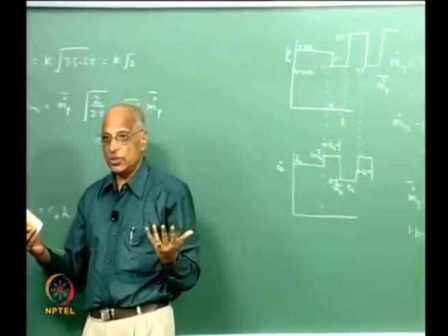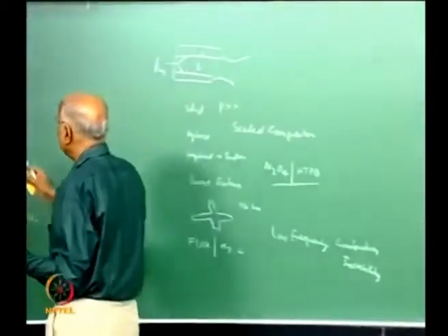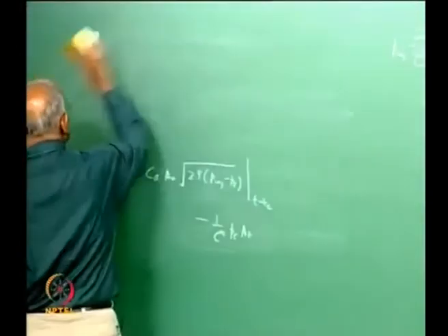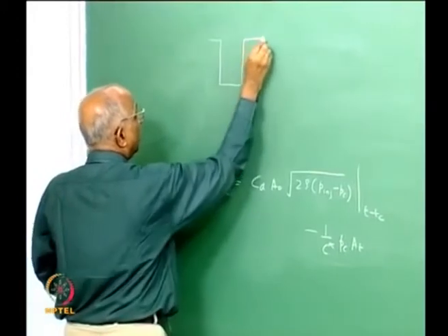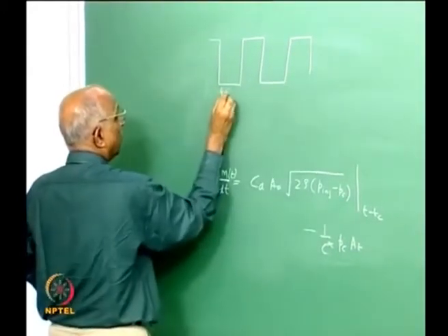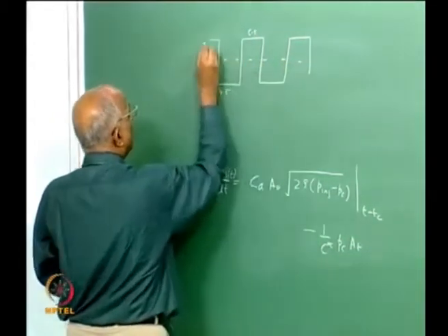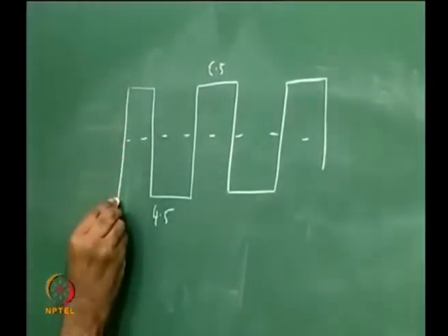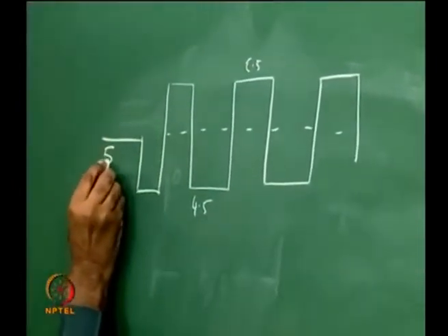Out of a steady situation, with this delay term, you started getting oscillations. The oscillations are neutral, in that it keeps fluctuating between 4.5 and 5.5, whereas the nominal value before the drop was 5 MPa.